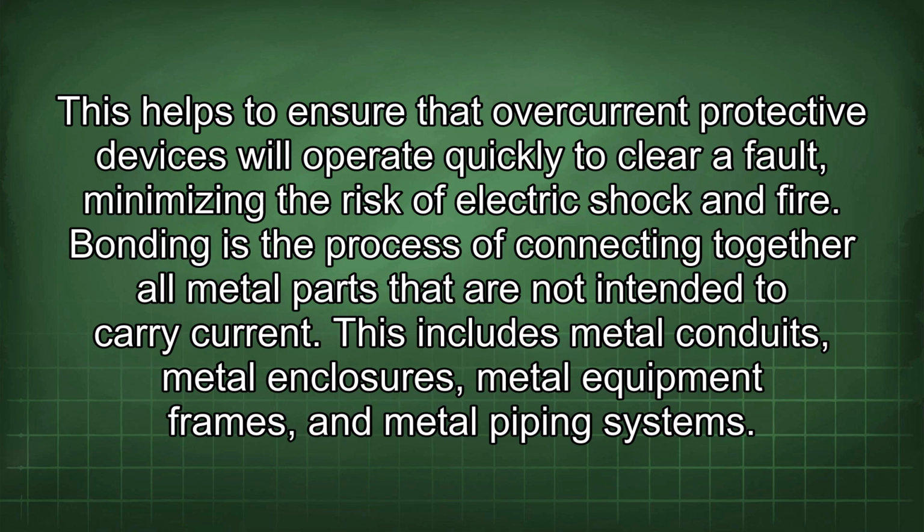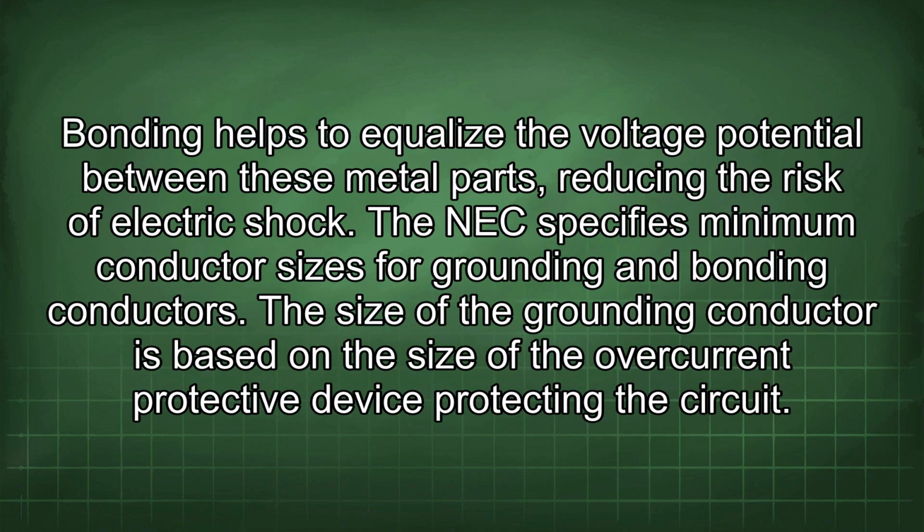Bonding is the process of connecting together all metal parts that are not intended to carry current. This includes metal conduits, metal enclosures, metal equipment frames, and metal piping systems. Bonding helps to equalize the voltage potential between these metal parts, reducing the risk of electric shock.